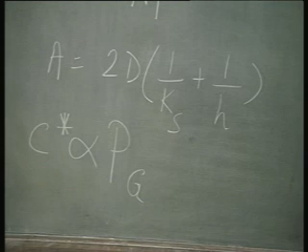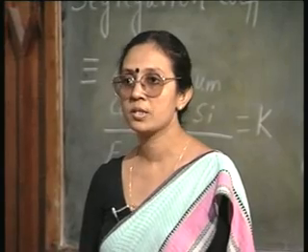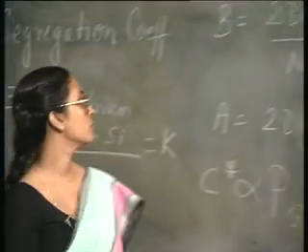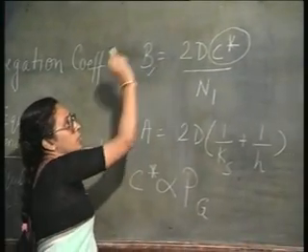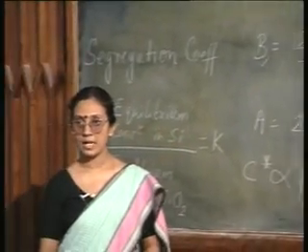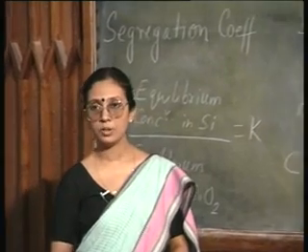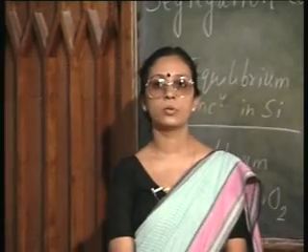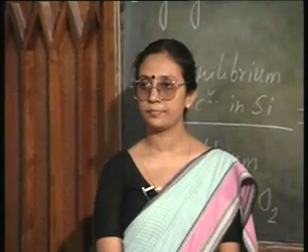So, if you raise the pressure, if you carry out oxidation under high pressure, you are going to increase both B as well as B by A. Both the linear and the parabolic rate constants are going to increase.